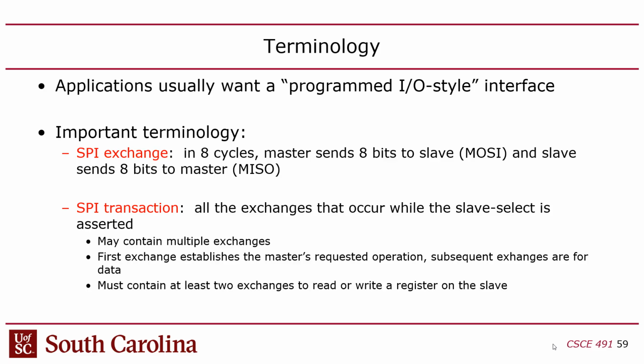Both of those things are not bidirectional. They're a half-duplex operation. Because if I want to read a register, I send the address, and Homeboy sends back the data, right? So when I send the address, half-duplex, because only one person is talking. When I receive the data back, half-duplex, only one person is talking. So there's no need to do this exchange business.